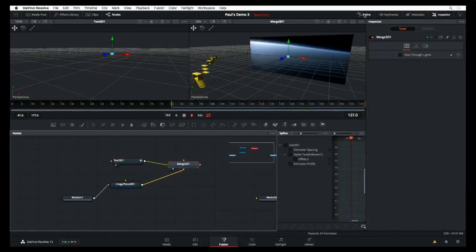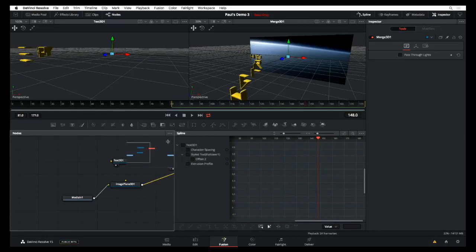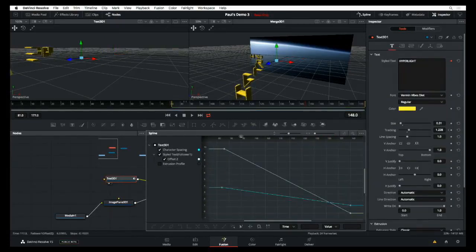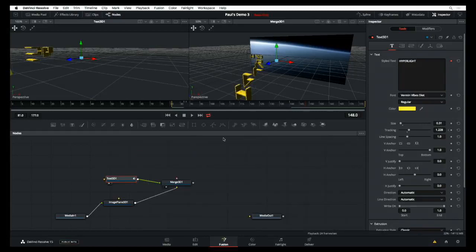The animation is very mechanical right now. So we can go into our curve editor. We have full control over our animation parameters. I can select these. I can adjust the curves for any parameter. So the ease in, the ease out. We've got all different kinds of tools here. So you can ping pong, reverse animations. You can stretch, squish, retime the animation parameters. It's a really, really powerful window in which you can completely customize your animation.